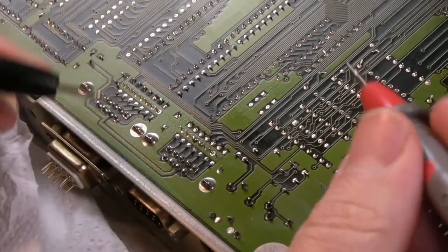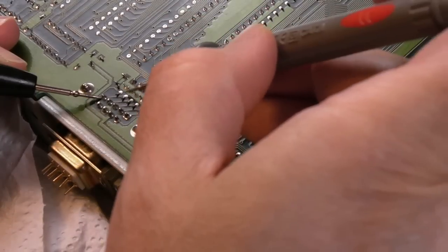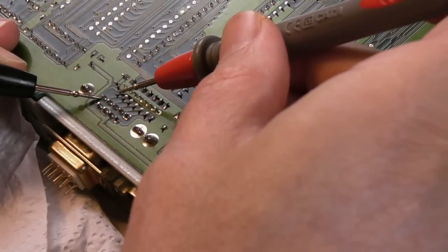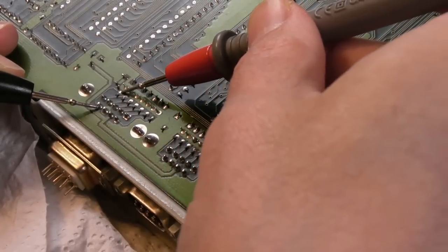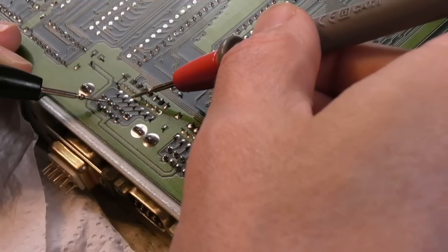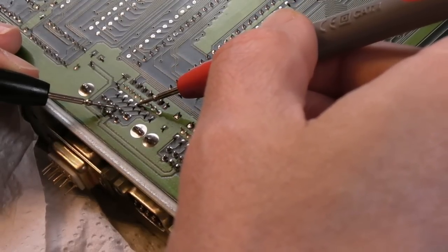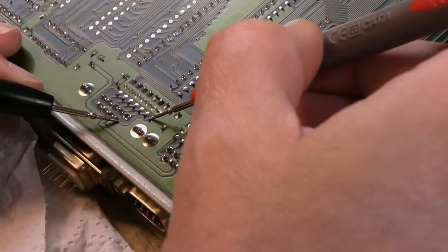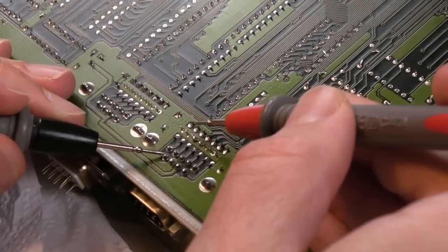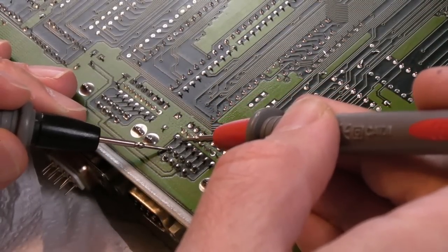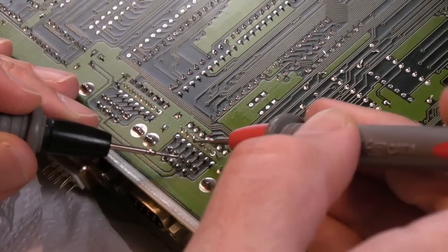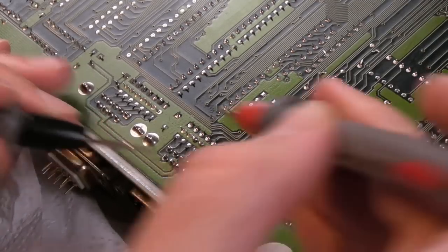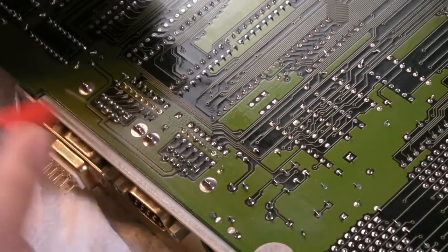Right, let's do the Occam's razor check first, the simplest stuff. Just checking the connections from the actual ports here, along with fine traces to the EMI components. So we'll start with that one down there. Just making sure each one joins from pin to pin here. Because those traces are pretty fine, it could be some corrosion. But anyway, that port looks alright. And then we'll check the EMI things next. Because maybe one of them's blown open. And I obviously soldered the bodgy solder things there. That looks nice and clean now. So there's no problems with the actual ports themselves.